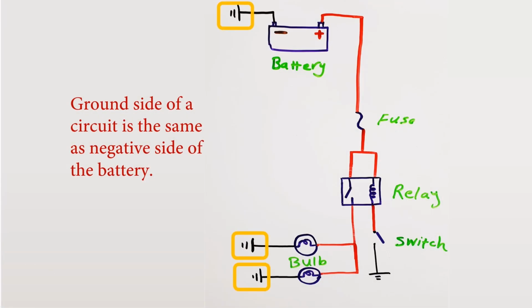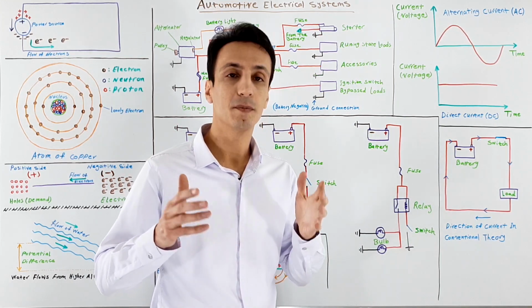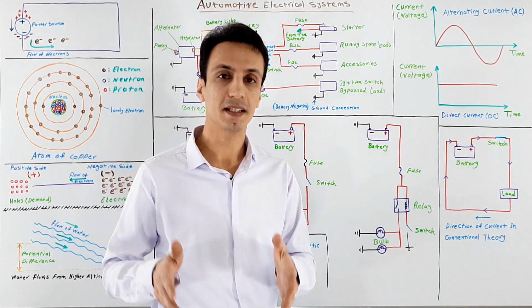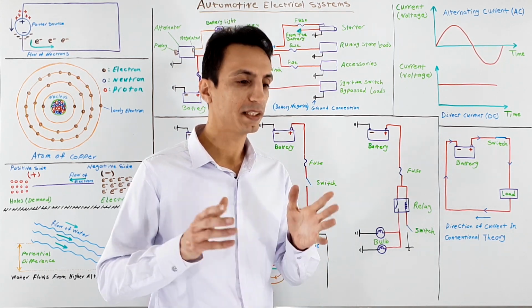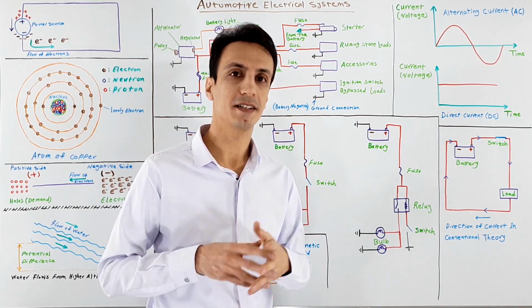We can say that on all the vehicles, when we are talking about the ground, we are talking about the negative post of the battery with zero reference voltage. And remember that almost all the body of the car is connected to the ground.